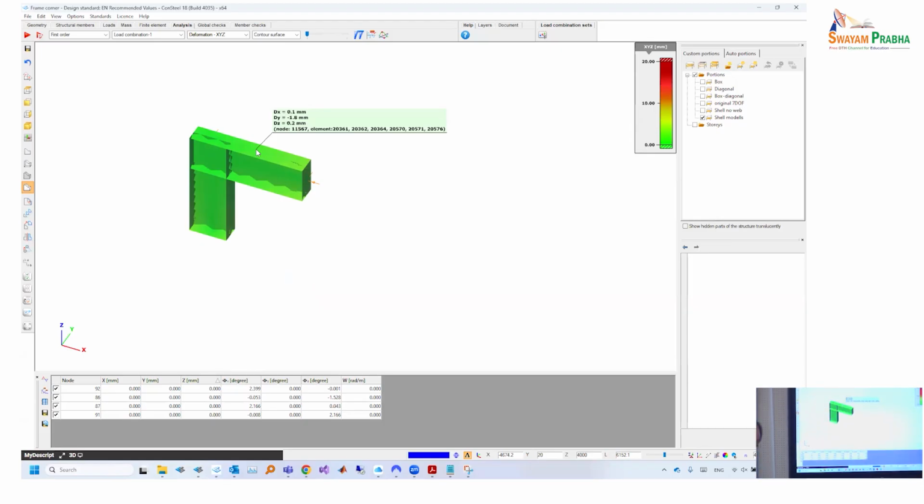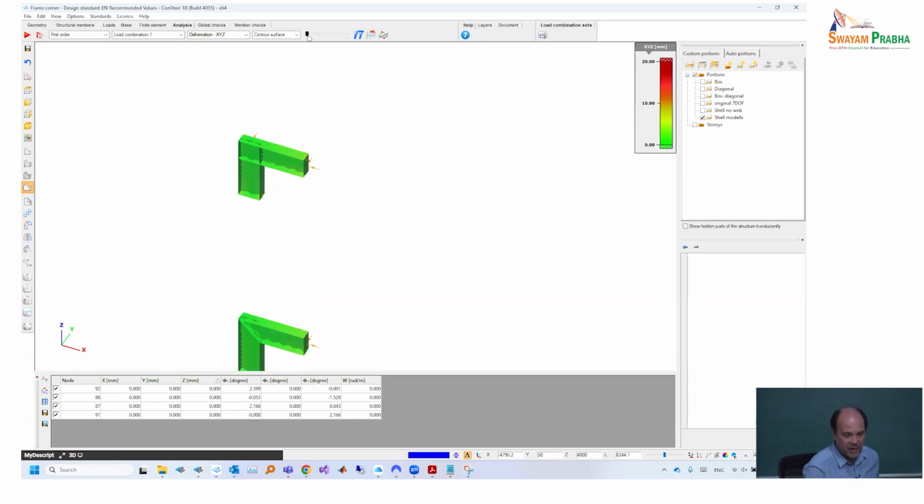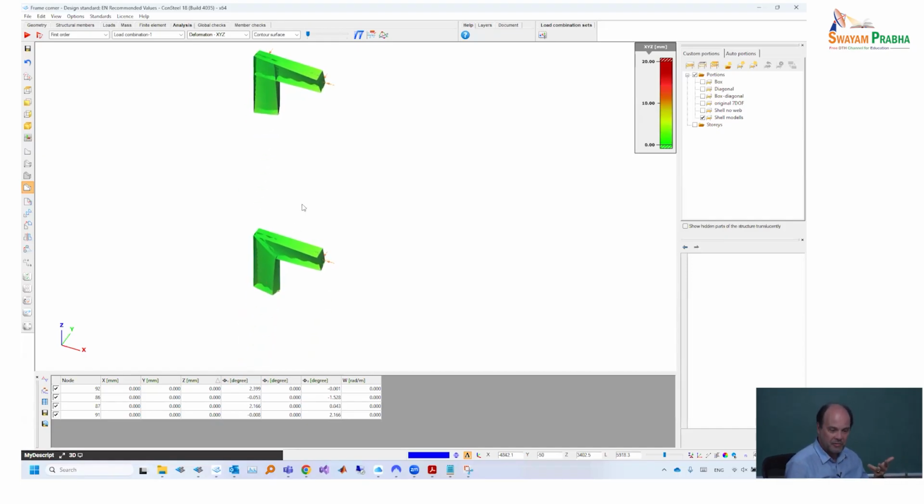For the first, for example, for the box, which is probably the most interesting and most surprising, given the fact that it gives exactly the other type of rotation from what the beam element by default would do. Our beam element by default does this. So if we just accept the analogy of the two bending moments, then we would always believe that, independent of the information about how the connection looks, the rotation is always like this. Now, in the case of the most commonly used solution, it is just the opposite.